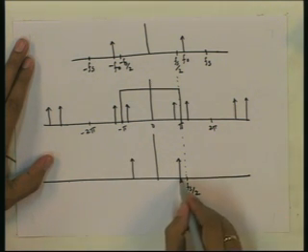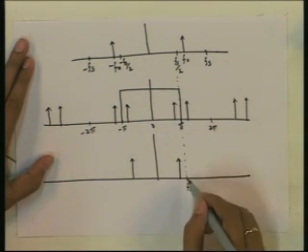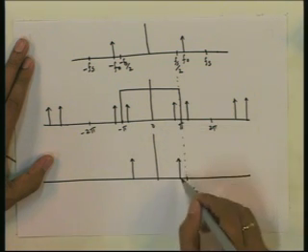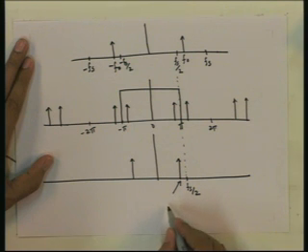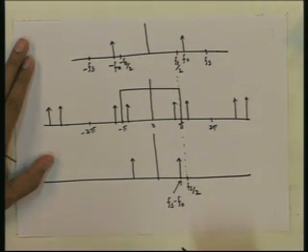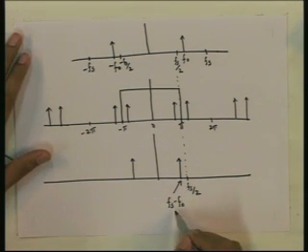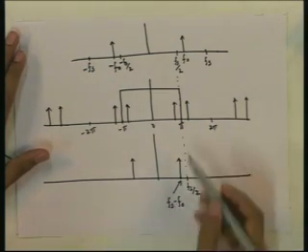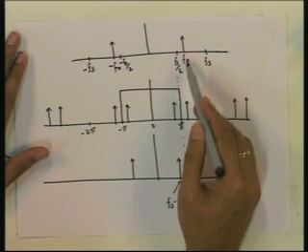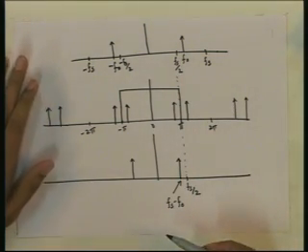And what will be this frequency? This frequency will be so that pi is mapped to this, then this is mapped to what? That is the frequency you will get, and that frequency will be simply Fs minus F naught. Okay. So, we see that the signal frequency that we have got after recovery of the signal is different from the original signal frequency. So, we have not recovered the signal correctly.